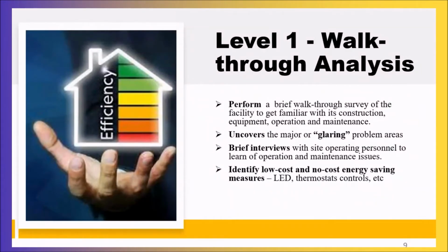In the walkthrough analysis, you will perform a brief walkthrough survey of the facility to get familiar with the constructions, equipment, operation, and maintenance, and to uncover the major or glaring problem areas. After that, you can have a brief interview with site operating personnel to learn of operations and maintenance issues, and to identify the low-cost and no-cost energy saving measures, such as LED, thermostat control, etc.